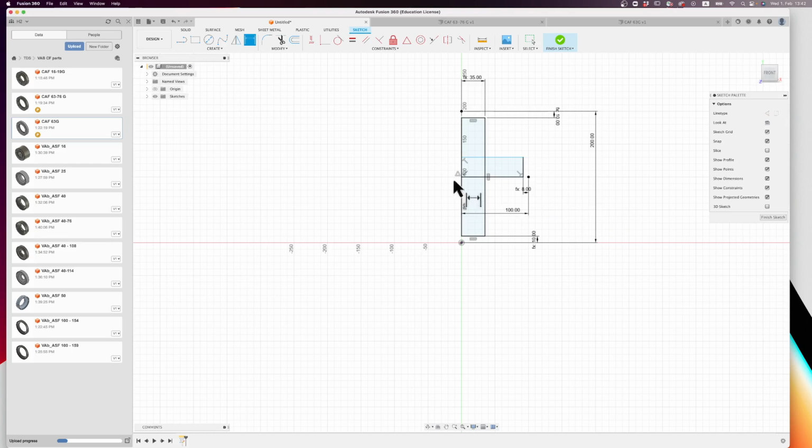And the next thing we're going to do is have something coming out our way here. So we might want to have some other flange that comes out at an odd angle that we're going to use a second sketch for. If it comes out straight, I could just pull a circle here and you're going to see later why I could. In this case, it would be relatively easy because you can just have it coincident here. We're going to do that with a second sketch.